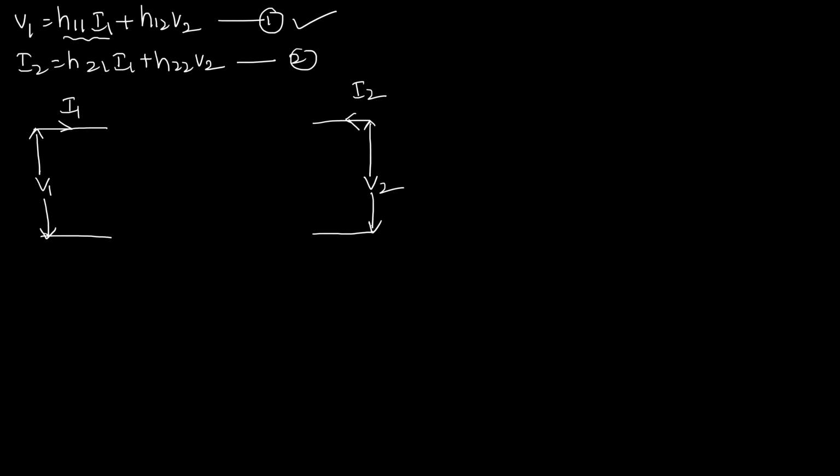That is a voltage equation, and we can find a voltage equation in a loop. So on the first port side, we have to represent a loop. In that loop, what is the first element? H11 into I1. So H11 will be considered as our impedance, like this. And look at the second portion, this is dependent on the second port voltage.